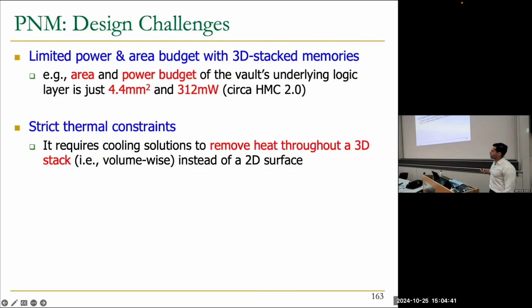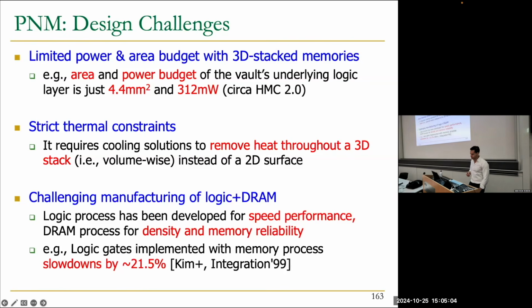And if at some point the processing capabilities of your chip become too costly and start generating a lot of heat, we need to move from passive cooling systems to more active cooling systems, which is an active research field for 3D-stack architectures, for example. So this means that it will be costly, and this also needs to be taken into account.